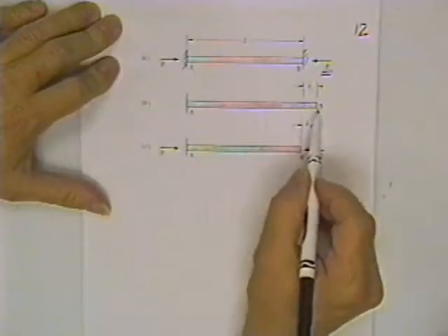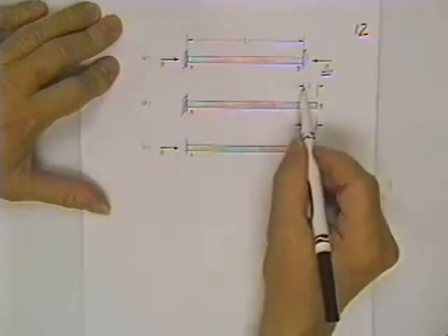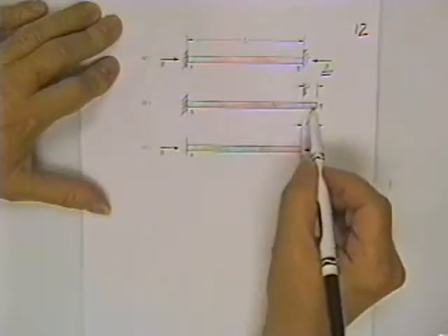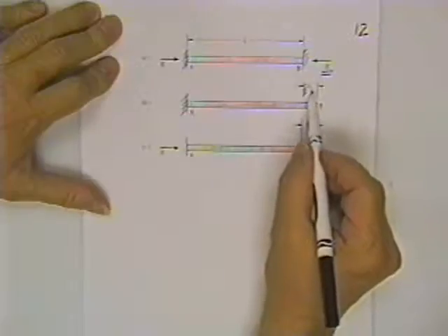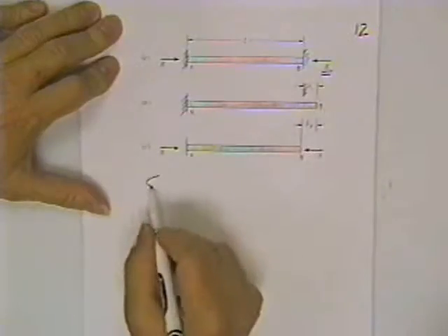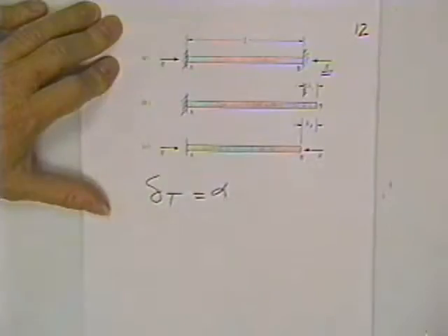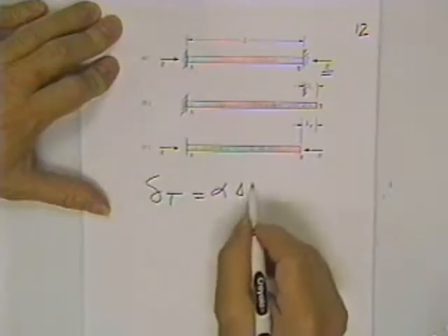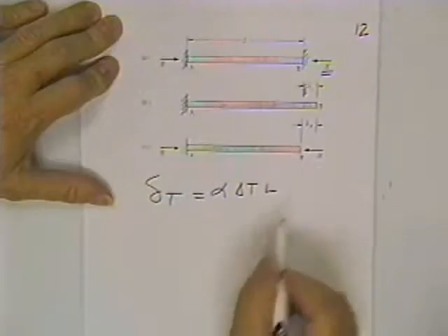He pretends the wall isn't there. He heats the bar. He lets the bar go ahead now and move to the right, however far it wants to, delta due to temperature. Delta due to temperature, we know, is alpha, it's in the book, or it will be given, delta T, the problem will have to state how much hotter the bar got, times the original length.